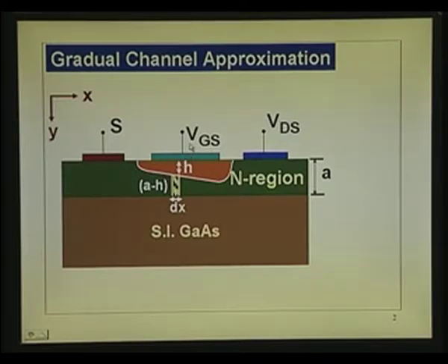So, we have used terminologies VGS, gate to source potential, and VGS has a positive value if it is forward biased, VGS has a negative value if it is reverse biased. And we also saw in the previous discussion that when VDS, drain source voltage, is small, the drop along the channel length is small. This region is called the channel. So, the drop in the channel region is small, and then the voltage across the depletion layer is constant from the source end to the drain end.